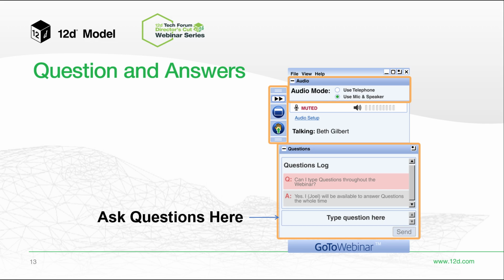Great. So Daniel has asked, what is the reason only the top area is used for the rainfall area and not the whole active area? That was just purely to show you that you could have individual and different valued rainfall areas. You'd probably want to do it on the entire grid, but having the ability to have separate or individualized rainfall areas, or you could even have a polygon, let's say if you're doing at source attenuation from a building and the building's never going to get into runoff, it just allows you to almost exclude those areas from the rainfall coming from the temporal pattern or from the rainfall on grid.